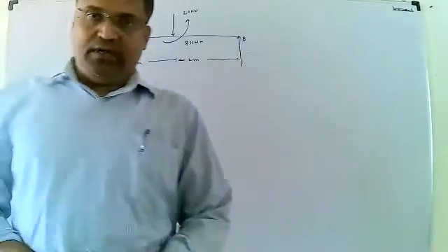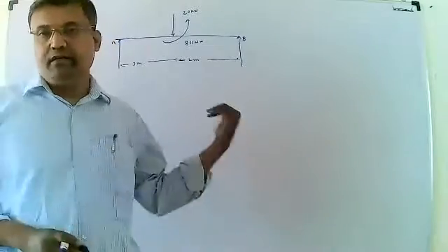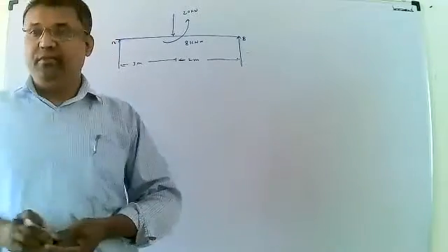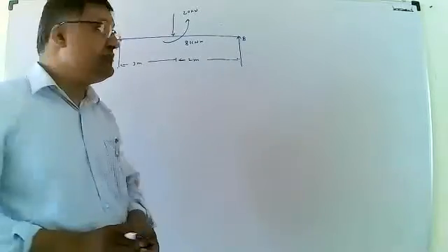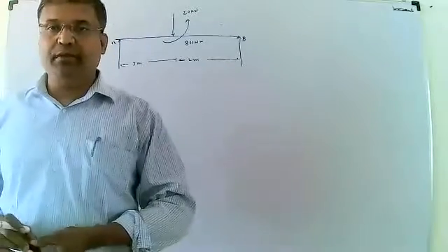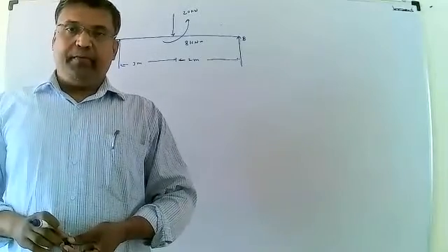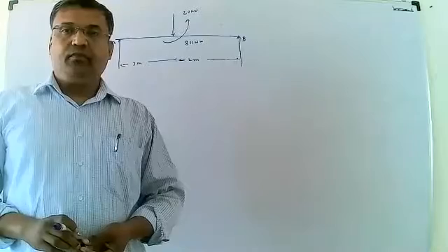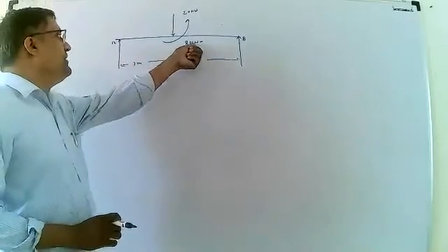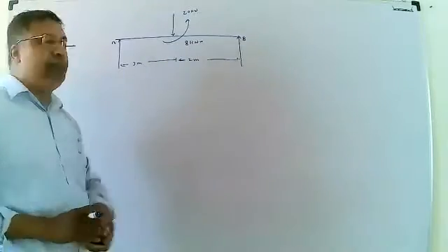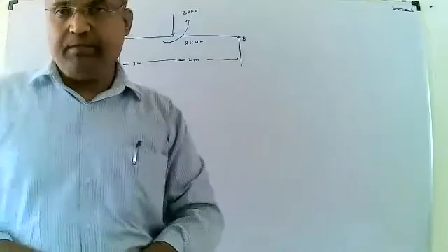Then here, first we calculate the reactive forces according to the equilibrium conditions. A simply supported beam is given, which is provided with a point load at the middle of the beam. Then, to draw the SFD and BMD, a couple is given. Here, an 8 kN·m moment is given. That moment is anti-clockwise.